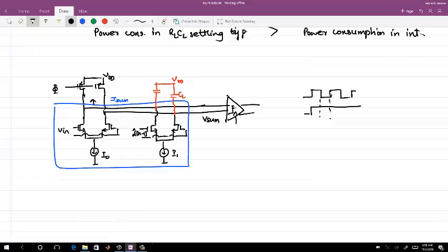Okay, let's say it adds more capacitance, and that capacitance I can always take into account as a CL capacitance. There was a discussion whether the CL should be an external capacitance or the internal capacitance of all the transistors connected. And the answer is, to an extent, it should consist of all the internal capacitors of the circuit. The external capacitor which you add is only to control the output swing.